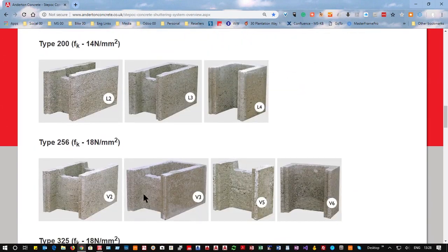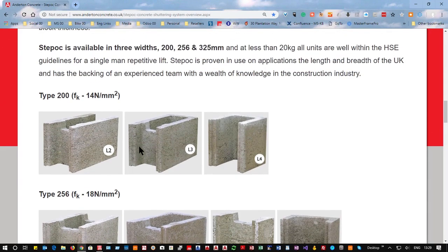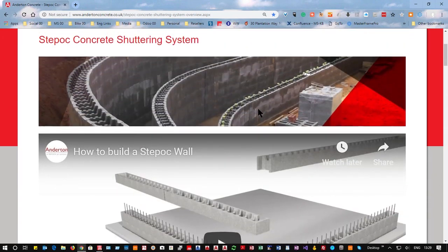The reason is that it's got these little notches in them, and the little big notch as well. That means these are built without a mortar joint between the blocks horizontally, and these little notches hold the distribution steel, which also then holds the main steel in location at the right point. So you have a lovely fair-faced wall finish with no mortar joints or anything.